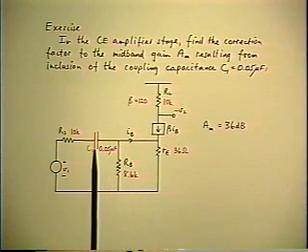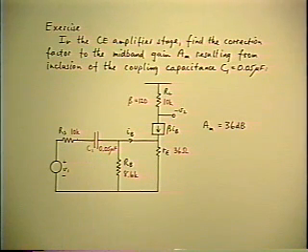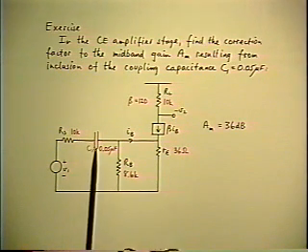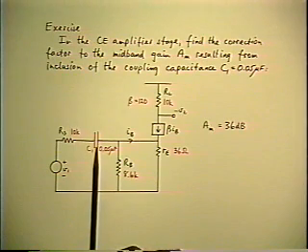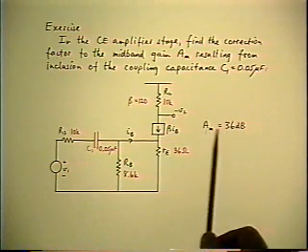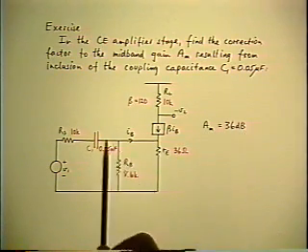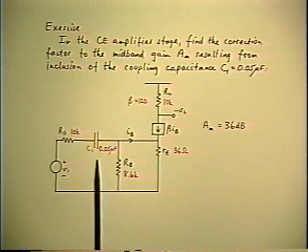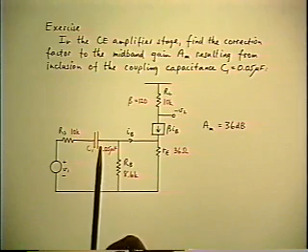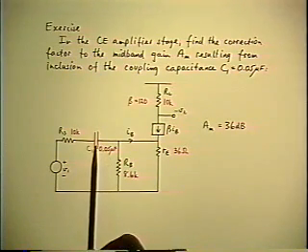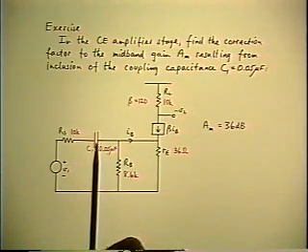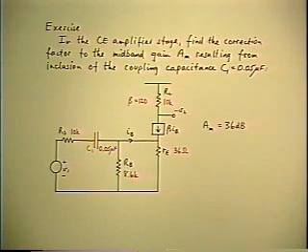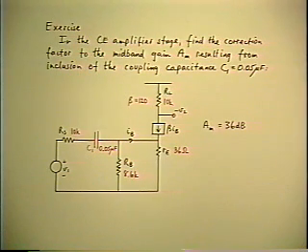But let's put the spotlight now on the coupling capacitor, which up to now we've taken to be an AC short, which leads to the same mid-band gain of 36 dB that we had before when C1 acts as a short. And so the problem now is we want to account for the coupling capacitor, so we treat it as an extra series element whose reference value is zero impedance.